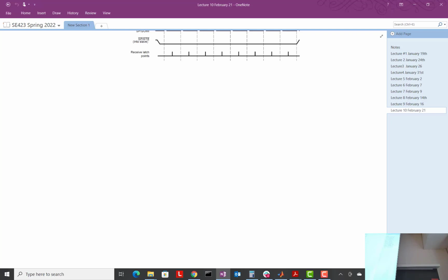Very fast ADCs. Well now, because they can make things really small, they put the sensor in the chip, like for an IMU. They put the sensor in there, and there's a little processor in there that's sampling that with ADCs or whatever, digitizing it, and then sending it to us digitally. Why do they do that? Well, sending an analog signal is always susceptible to noise, right?